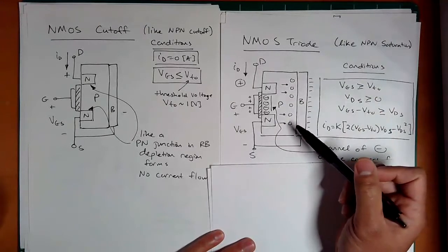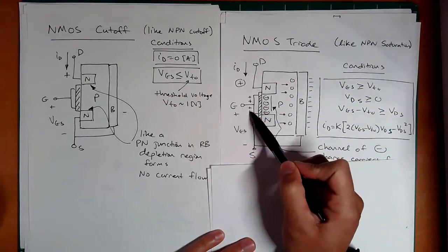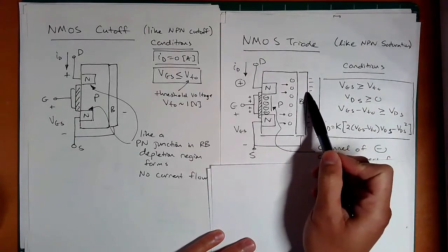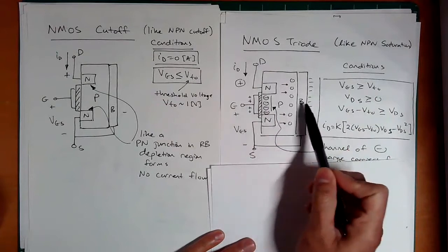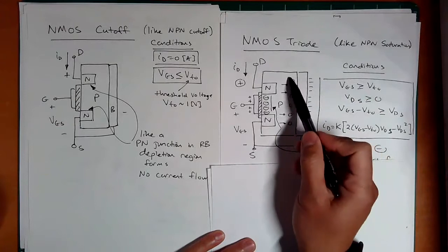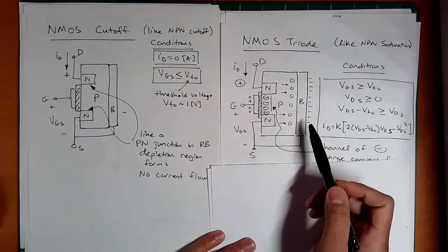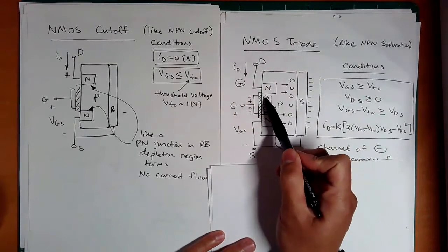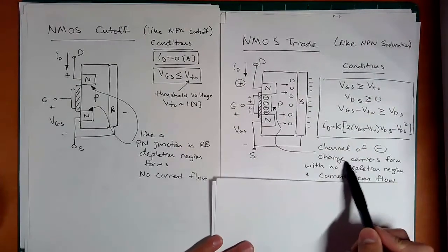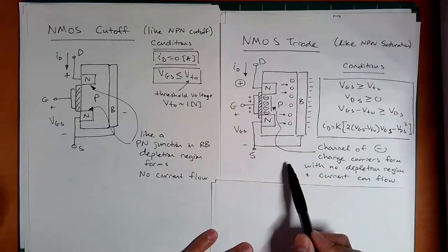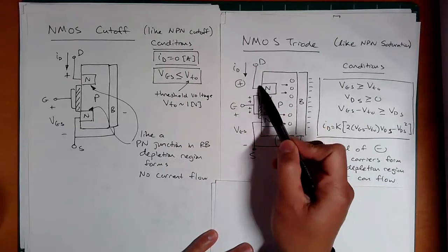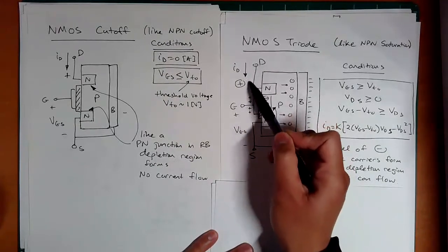And so what's happening physically? Well, imagine you're getting a charge buildup on this oxide plate. And look how you got this source attached to here, the body. And so you get this negative, so you have positive, negative. And you have a p-type material. And this p-type material, if you recall, all the little holes are being pulled to the right, which is equivalent to having all these holes filled with electrons. So what do you have? You have a channel of negative charge carriers right here with no depletion region, forming a path for current to flow all the way down. So that's kind of nice.